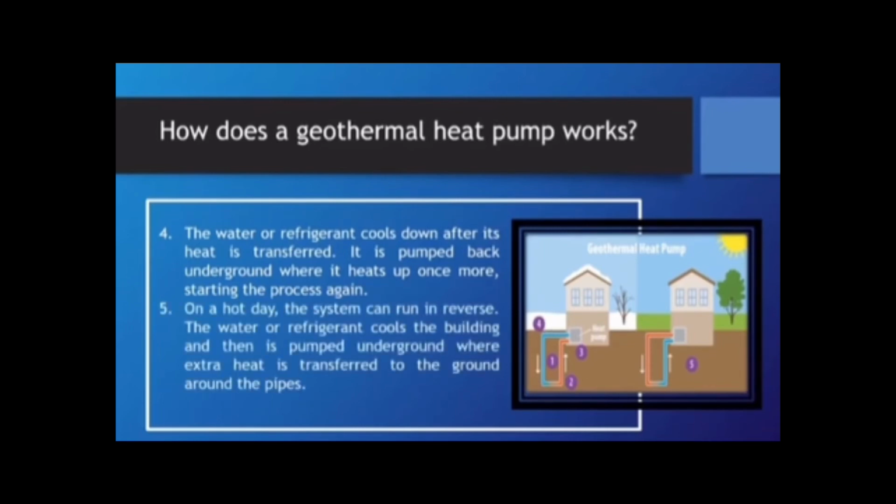And lastly, on a hot day, the system can run in reverse. The water or refrigerant cools the building and then is pumped underground where extra heat is transferred to the ground around the pipes. Let us now proceed to the different types of geothermal heat pump systems.